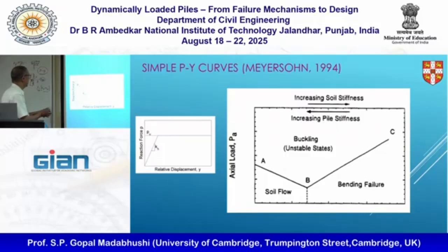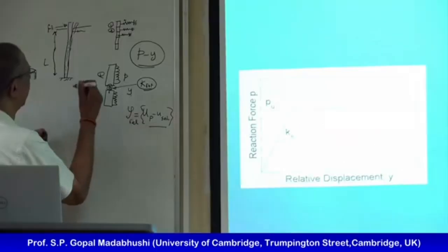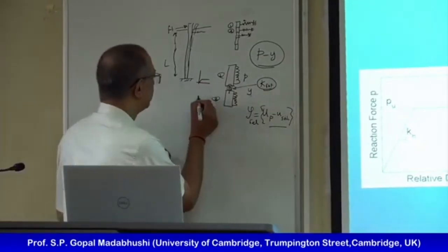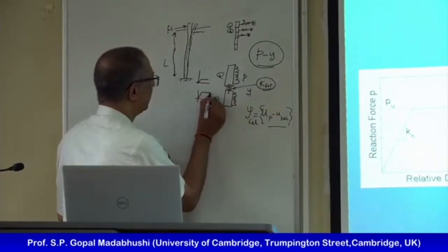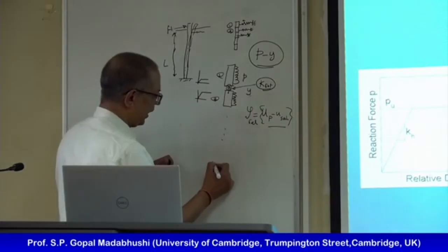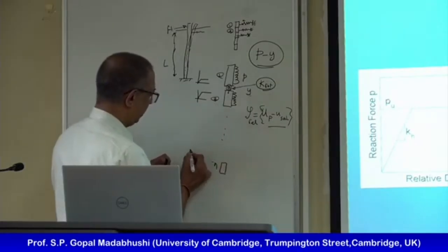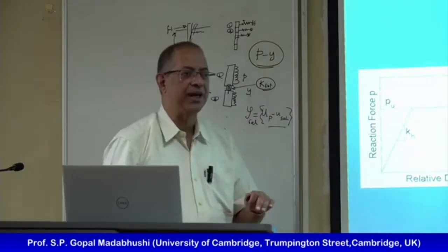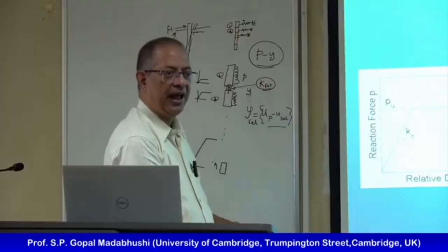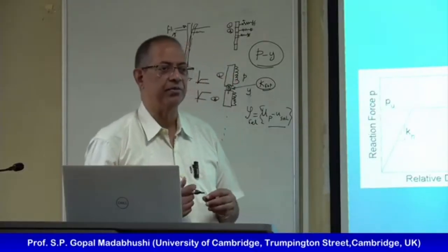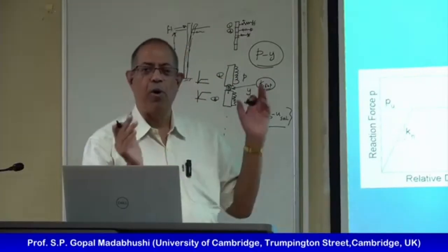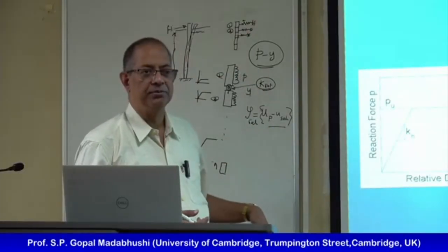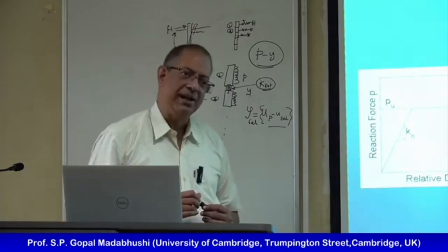Now what you can do is say, for element number 1, I have that. Element 2, slightly bigger. So the nth element here will have quite a big force like that. So the PY curves we can change depending on depth, and then it gets quite realistic. We are not saying one PY curve for all the elements. The PY curves themselves are scaled up depending on how deep you are. We're still not changing the stiffness.